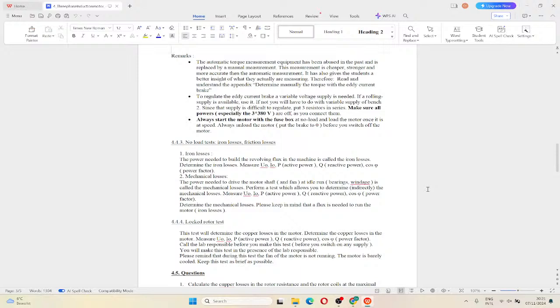So NS is basically 50 hertz times 60 seconds over P, so it's over the number of poles over 2. So it's like 60 times 50 over 2. But it's measured here. Yes, that is. And N is what we need to measure. It has 2 pole sets. Yes, I guess so. Because it has over 2. Yes, it's like 60 times 50 over 2. And N can come from the tachometer.